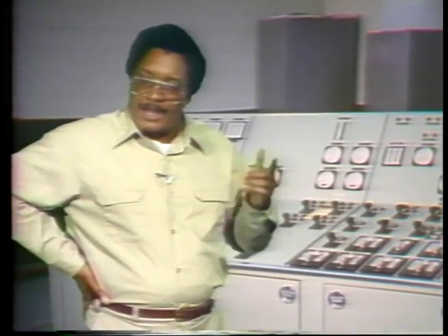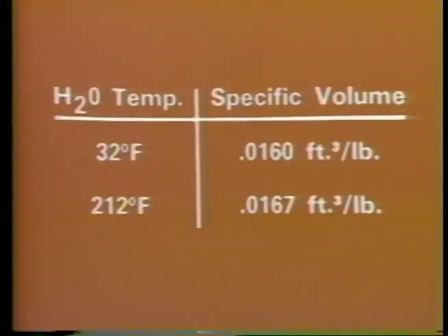Since the temperature of the steam-water mixture is not changing, specific heat does not change while water is converted to steam. However, specific volume is greatly affected by the boiling process. As you'll recall, the specific volume of subcooled water changed very little as heat was added.